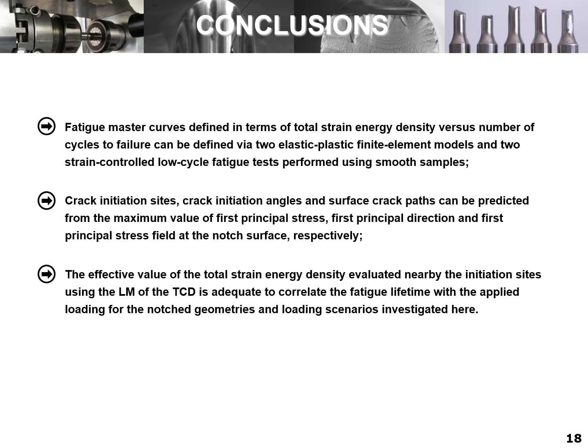Finally, a few conclusions. Fatigue master curves defined in terms of total strain energy density versus number of cycles to failure can be defined via two elastic-plastic finite element models and two strain-controlled low cycle fatigue tests performed using smooth samples.